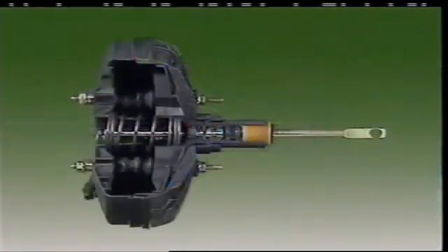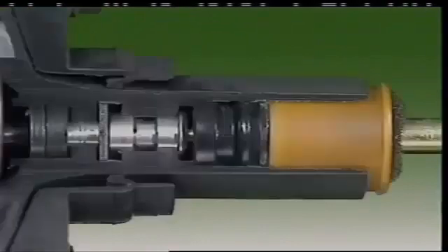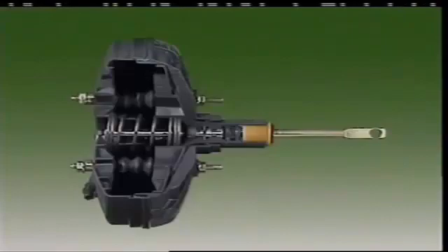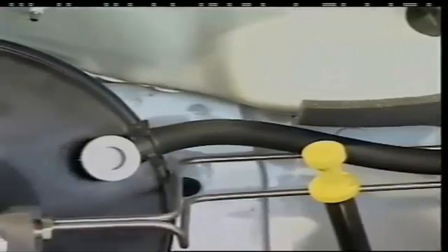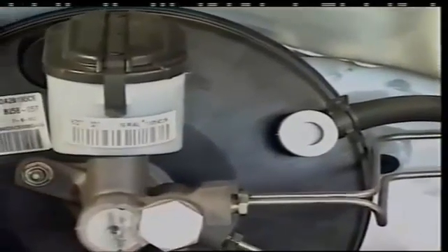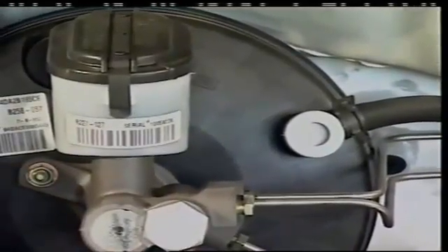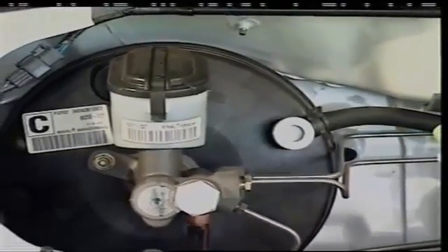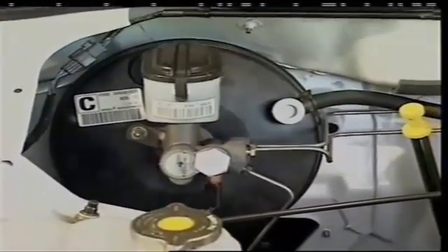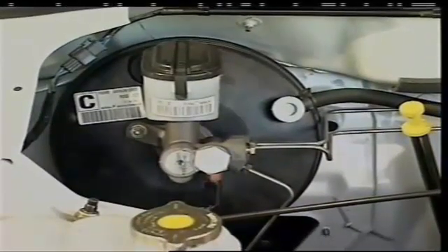It also operates a control valve that admits air at atmospheric pressure to the rear of the unit. How it works depends on the position of the pushrod. A hose connects the intake manifold to a vacuum check valve on the power unit. With the engine running, the vacuum in the intake manifold is used to evacuate the power unit. This valve is held off its seat and a vacuum is produced in both chambers of the unit.